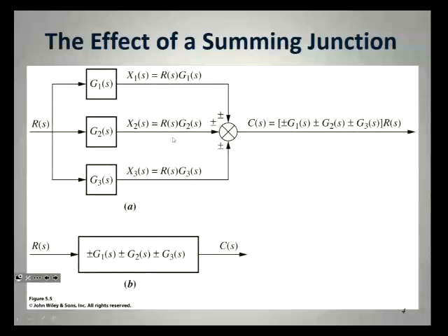These are ones where you're putting an input multiplied by some transfer functions in parallel, which you might get, for instance, with PID control. You did a cascade one, but you could have parallel PID, that's quite common as well. So the idea is you would multiply R(s) by each of the transfer functions and then add or subtract them as necessary with your summing block. Again, I think that's quite straightforward. You could write it like that, or as G1 times R plus G2 times R plus G3 times R. Same thing.